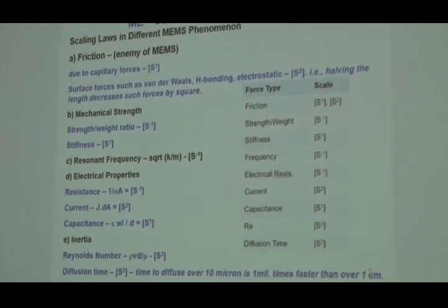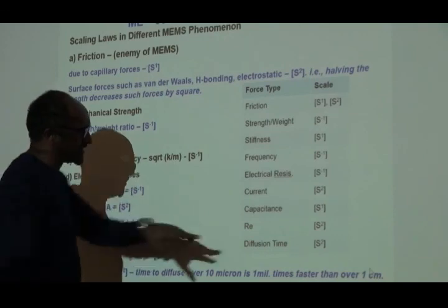Okay, that's obvious. You reduce the size. Omar, what happens with the frequency? If you have a material, you have a beam, it has a certain frequency omega. If I reduce it by 10, what do you think happens to the frequency? Is it going to vibrate faster or slower? Faster, right? So you reduce the length, the frequency increases.